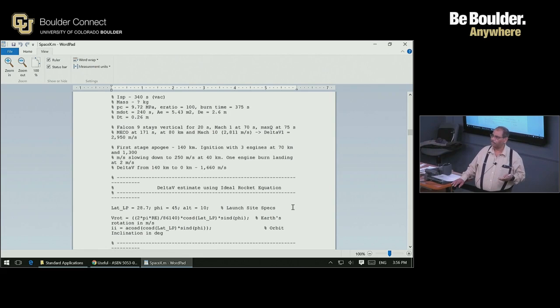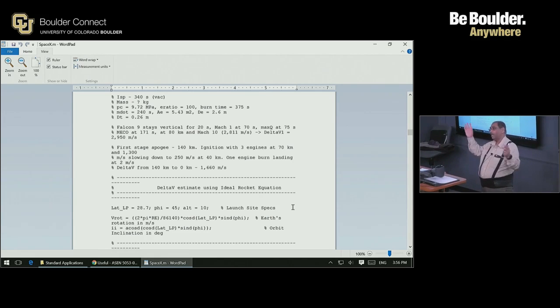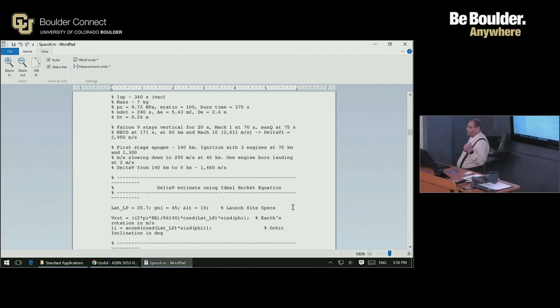Now, you can't have it too high because it requires higher thrust, which means more powerful turbopumps. On the other hand, you can't have it too low because it will then take forever to clear the launch pad and accelerate towards the target. Missiles, on the other hand, have a very high thrust-to-weight ratio because they have to get to the targets pretty fast.